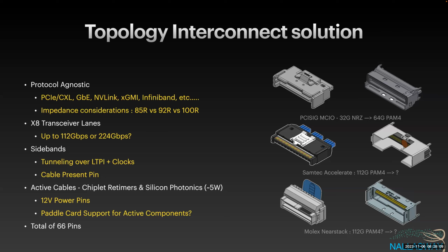Sidebands. We really do need sidebands because the way this module is going to work is it's going to power up the BMC, the system manager, and actually discover what's plugged in. There are a number of other work groups within OCP working on this, like CMS, composable memory systems, trying to discover the memory network. So we need to do that. I personally believe that we've been stuck in the 1970s with sideband management, and I want to get over that and escape it properly.